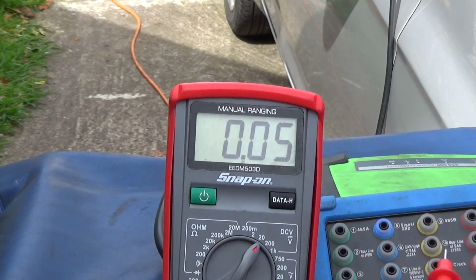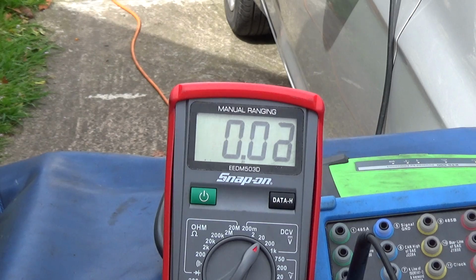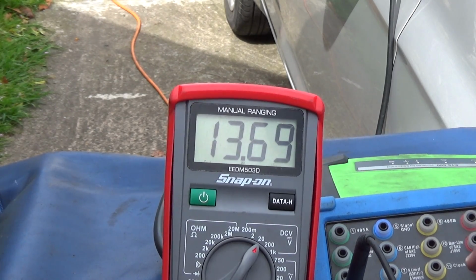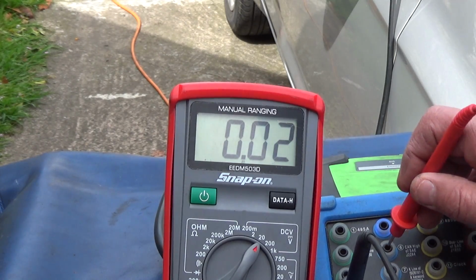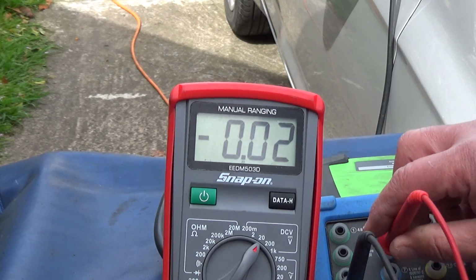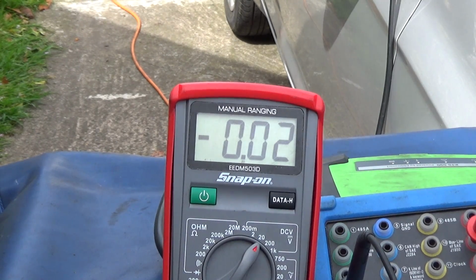Do a plausibility check with our meter first, so to battery ground, chassis ground, and pin 16, which is positive. Okay, so there's our battery voltage, so we know our meter's okay. We'll leave the ground in there, and we'll check pin 6 first, the CAN high. No voltage on that, and 14, no voltage on that. And we'll turn the key on.